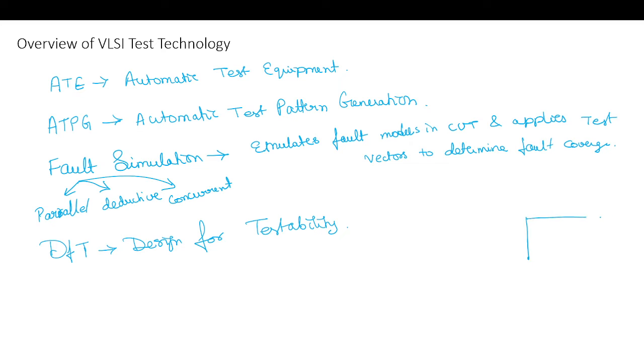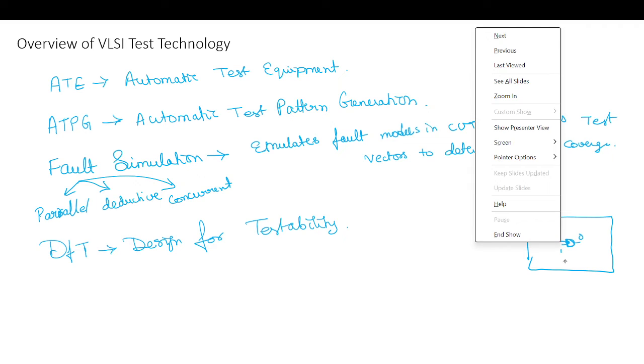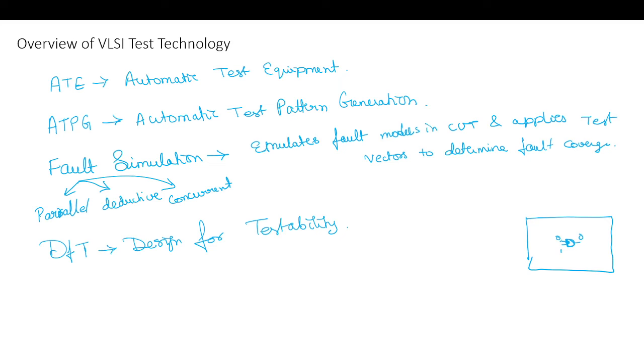Say now I have an IC. Here I have, deep inside, an AND gate. We said 0, 1, 0. If we have this pattern, we can detect certain faults, say the F1 fault. Now to get this value to 0, we can't control it directly. We only have access to these pins, so it has to come from deep within this sea of gates.